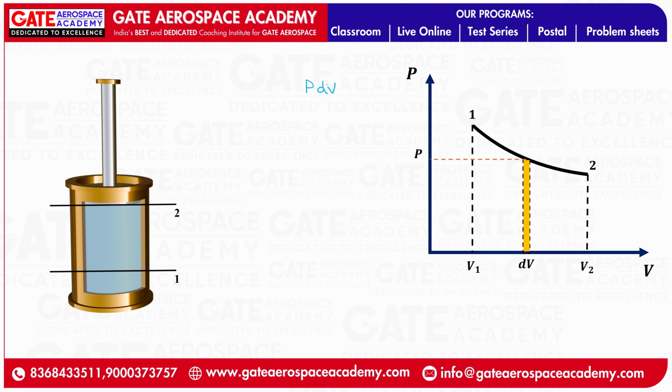Now if I want to find out the complete area under this path from state 1 to state 2, this will be the complete area. So how can I find it out? We have to integrate it from point 1 to point 2. But this is the work done. Just now we have proved this is the work done, correct? It means that we can write work done is also the area under the PV curve.